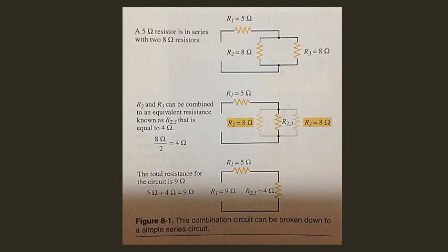8.1 Reducing a complex circuit. When solving a series parallel circuit, often called a combination circuit, you will use all of the formulas and techniques that you learned in Chapter 6 and 7. When one branch of a parallel circuit has resistors in series, you will use the series circuit formulas to turn those resistors into one equivalent resistor. When you come across parallel branches in series with other resistors, you will use your parallel circuit formulas to turn those resistors into an equivalent series resistor.